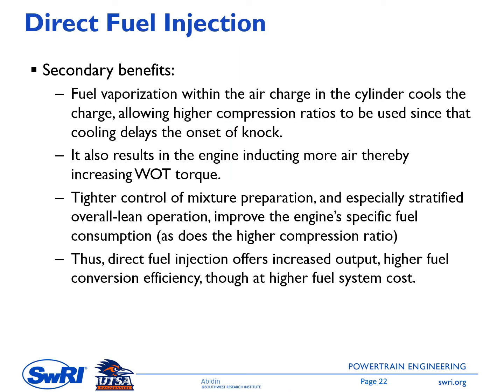Back to direct fuel injection, besides the primary benefit of this direct fuel injection method, we also have secondary benefits. The first one is that the fuel evaporation within the air charge in the cylinder cools the charge, allowing a higher compression ratio to be used since the cooling delays the onset of knock.